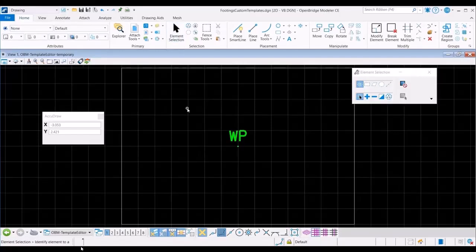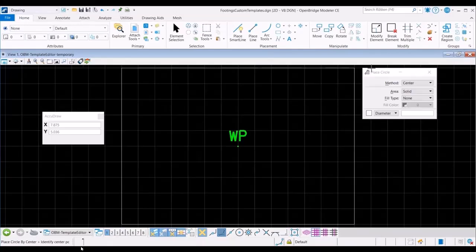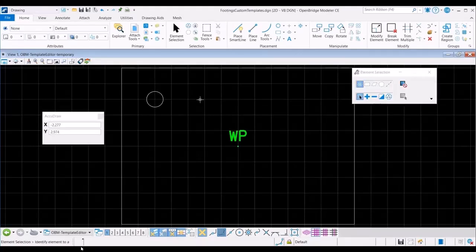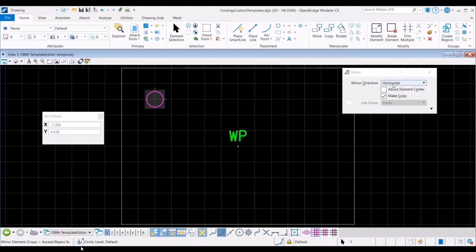To start, then, to locate piles, I can just reference this, just as a point, right? It's not that you're drafting the right side of the pile, because you can change it. This could be a representation. This is just a location representation, put it that way. It's not that, oh, this is going to have to be a circular pile, or I have to place an H shape, so it's going to be an H shape pile. No, this is just pure location. And then you can start placing, of course, how many you need. Yes, you have to place all the locations. It's not like, oh, I'm going to place 4 and then at the end decide that it's going to be 12. Right now, you have to specify every location of the pile that you may want.